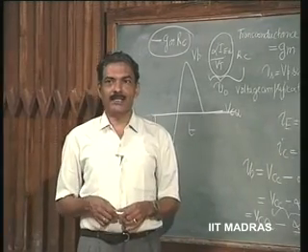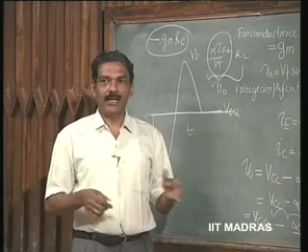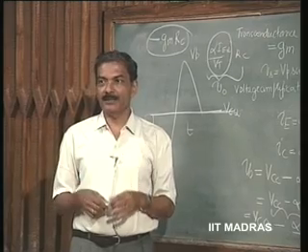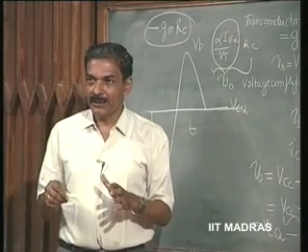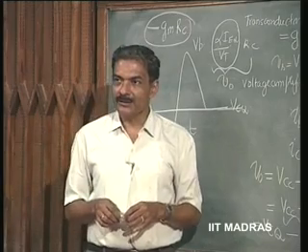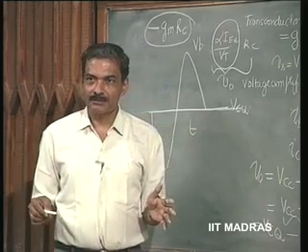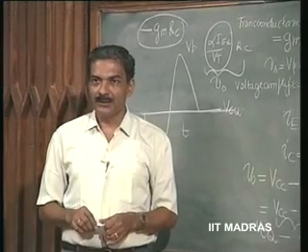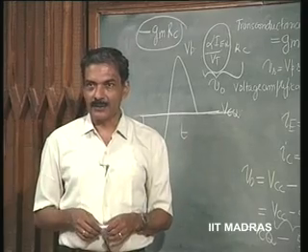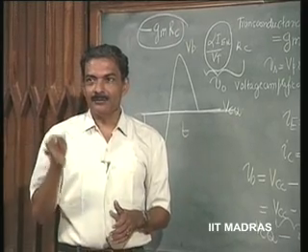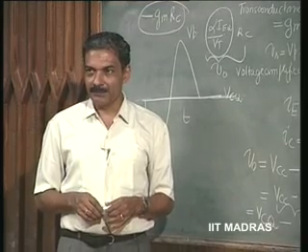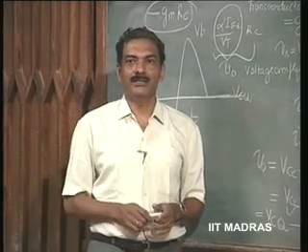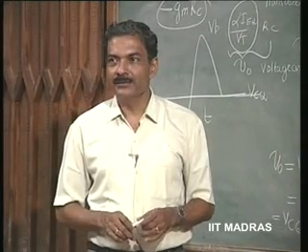So, if Rc is let us say 1 kilo ohm and operating current of the transistor is 1 milliampere, for which we are assuming that the transconductance is 40 millisiemens, the gain of the amplifier is minus 40, simple voltage gain. Or suppose you are asked to design an amplifier with gain of, let us say, minus 100, and you have fixed the operating point at 1 milliampere, for which the transconductance is 40 millisiemens, then the Rc that you should select is 2.5 kilo ohms.